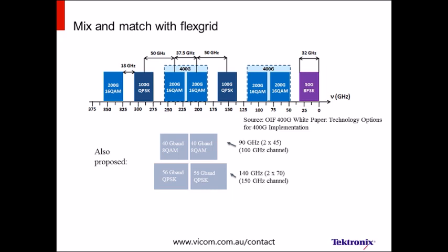One thing I wanted to point out is that the FlexGrid also makes possible the management of multiple carriers as one channel. So one WDM channel could actually have more than one carrier in that channel. And so we also need to deal with that, to be able to select out one carrier in a WDM channel and to analyze that particular carrier.